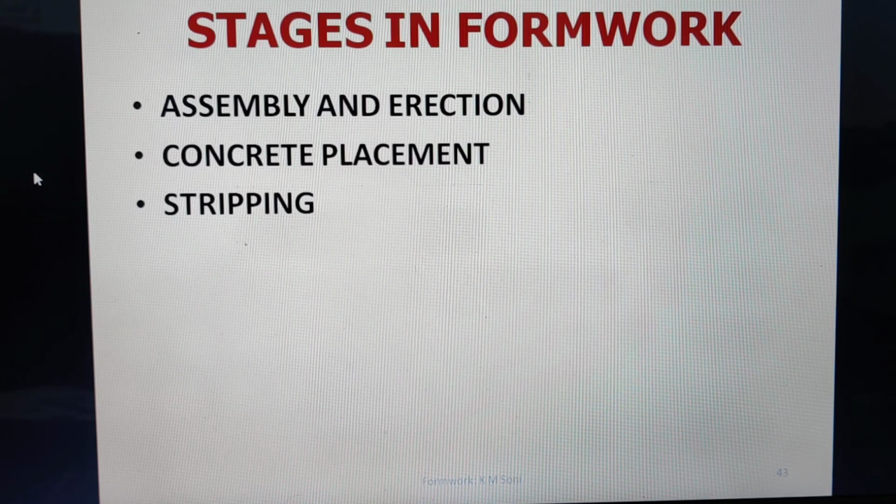Otherwise, formwork may not take that much load. So we cannot pile up concrete at one place. That should also be seen. And then the third part is stripping of formwork. So that is to be done after it attains the strength and in sequence.